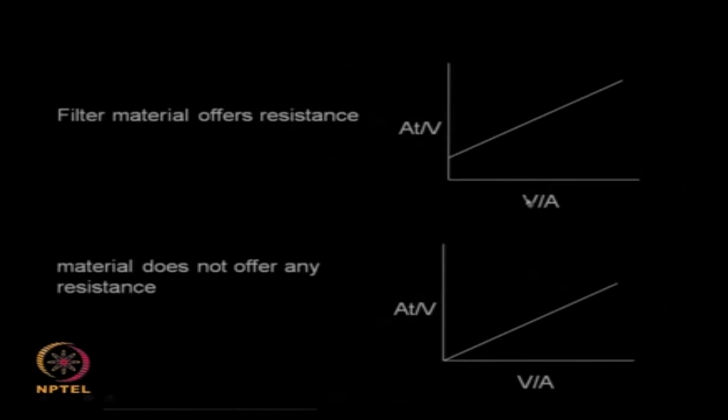Here V is the amount of liquid that needs to be filtered, T is the total time it takes to filter that, and A is the cross sectional area of the filtration setup. So it is simple. I take different amounts of slurry, filter them at a constant delta P, and calculate how long it takes to filter the different amounts.